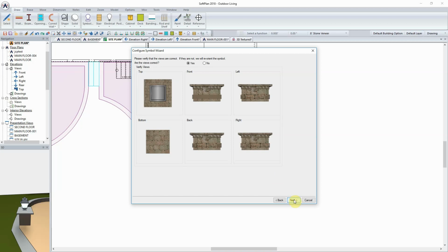At this stage, this is one of the more important steps that you're going to come across, and it's really the orientation of the symbol. You want to make sure that when you go to draw the symbol, everything is correct for what you're attempting to do, because it will impact when you go to draw a symbol. If you have the wrong side earmarked as the front, you'll wind up drawing symbols inverted to what you want, which will force you to have to do an edit with them.